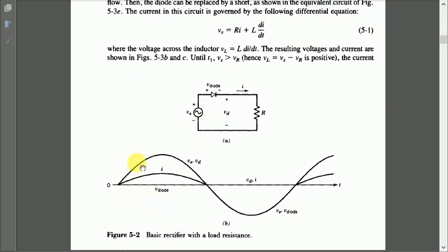And this is the waveform of the source voltage, as we can see over here, Vs. Now this waveform is only available over here in the positive half cycle, Vd, which they have given as the voltage across the load. So this portion only of the source voltage is available across Vd in the positive half cycle, while this portion, given the name of V diode, is available across the diode during the negative half cycle.